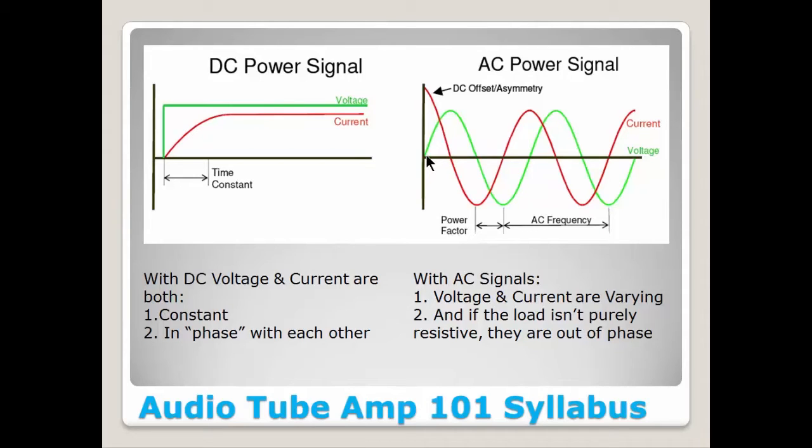What you got to realize here, though, is a speaker is not a resistive load. It is an inductive load. And when you're playing through a speaker, the current and the voltage are out of sync a little bit, right? So let's just pick a point in time, right? Let's pick this point in time right here where my cursor is at. At that point in time, voltage and current are in sync with each other. They're in phase at that moment in time.